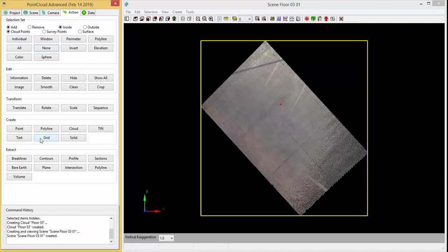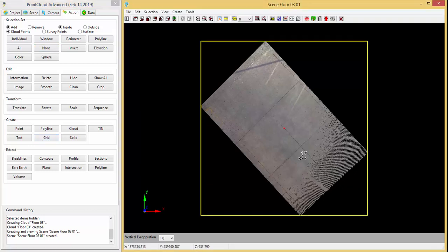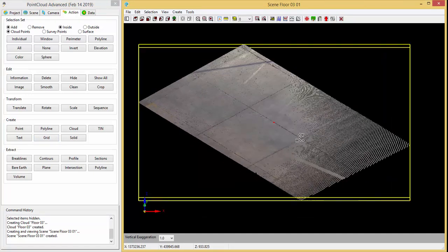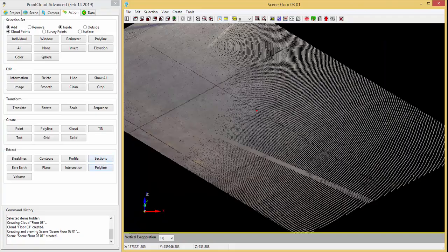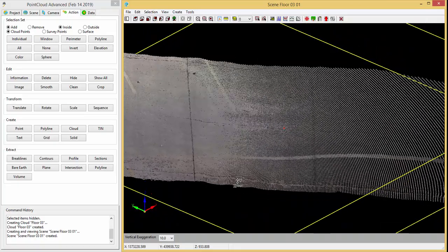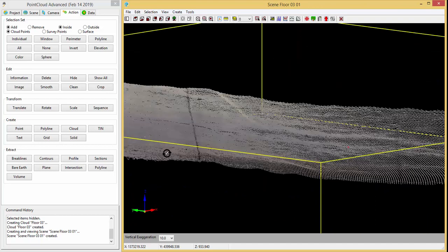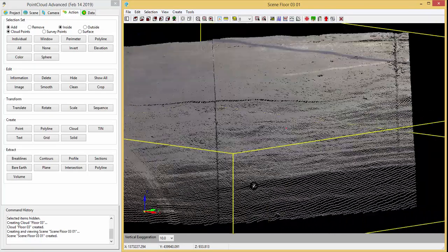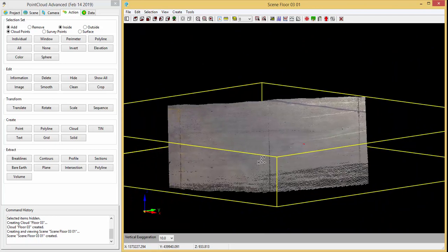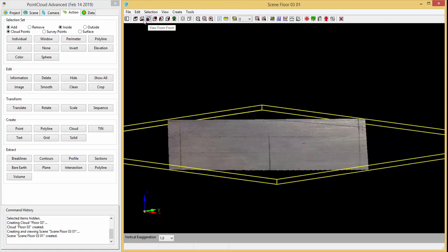So I'm going to pick grid, and another thing I want to point out is these little seams in between the panels are very low, and I want to ignore them. Here, if I window up, you can see that obviously these are low, and I'm more interested in just going from surface to surface from the high points, and ignore the low seams, which would maybe force a trend of it going down. So just something to be aware of how I create this grid. I'm going to do it from all the highest points, not the lowest points.